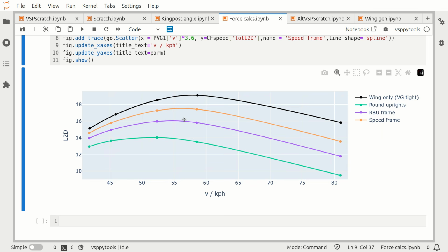Also bear in mind with all these figures, this would be in completely perfect still air. Now in reality, the days that we're flying hang gliders on, it's always a thermic day, so the air's going up in the thermals. That means that on average all the air in between is always going to be going down. So most of the time you're flying, you're either going to be in lift or you're going to be in sink. Even if it feels like dead air, there's probably still a little bit going on, so it makes it very difficult to get these numbers experimentally.